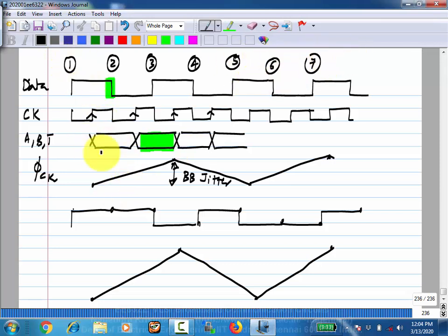Okay. So this edge 1 is the clock transition corresponding to that is too late. So that's why you are getting an up signal which is ramping up the phase. Okay. In response to 1, you are getting an up. In response to 2, you are getting an up, then 3 is down up to here, and then 4 is down, and so on. This is what is happening.